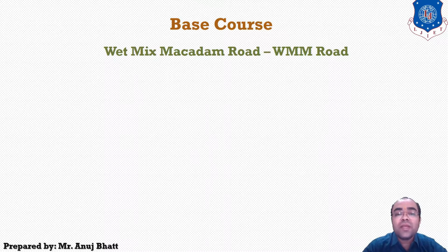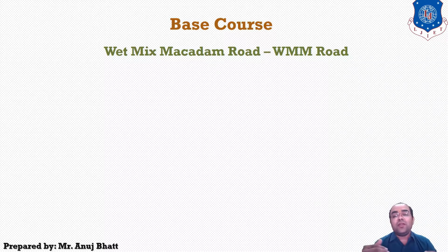So let's start the lecture with the introduction of wet mix macadam road, that is known as the WMM road. Well, wet mix macadam construction is an improvement upon the conventional water-bound macadam road, and this construction is intended to be an alternative and more durable pavement layer. Wet mix macadam is a base or sub-base course of the pavement, wherein clean, crushed graded aggregates and granular materials such as graded coarse sand are mixed with water and rolled to a dense mass on a prepared surface. The work may be done in different layers.